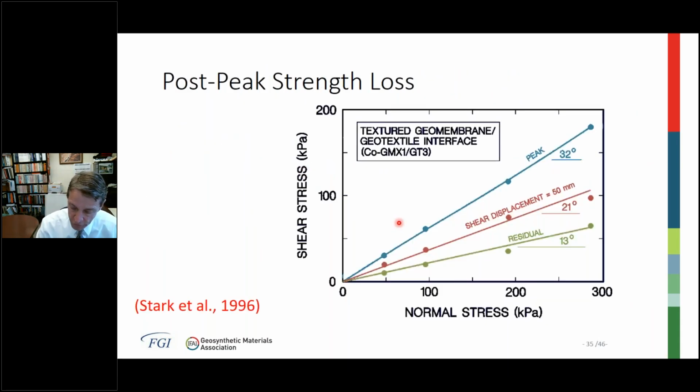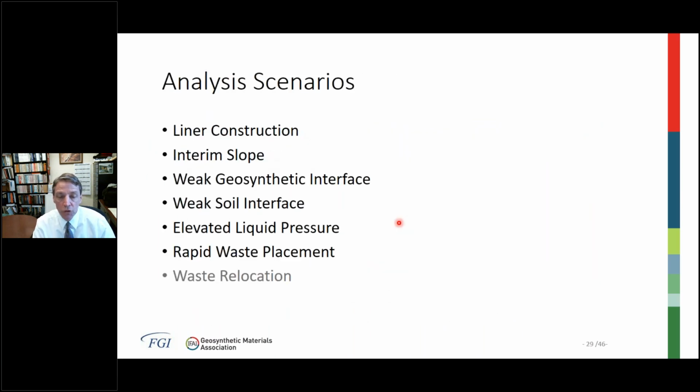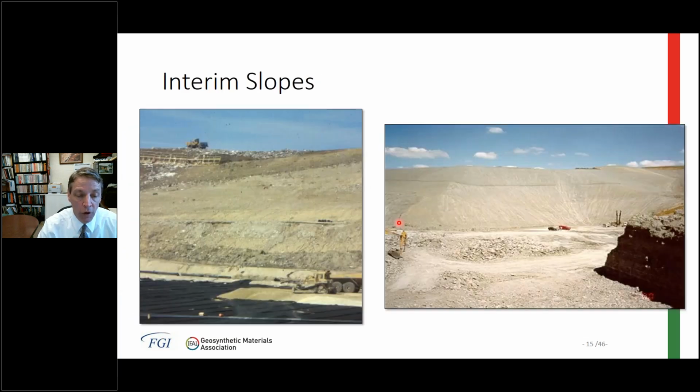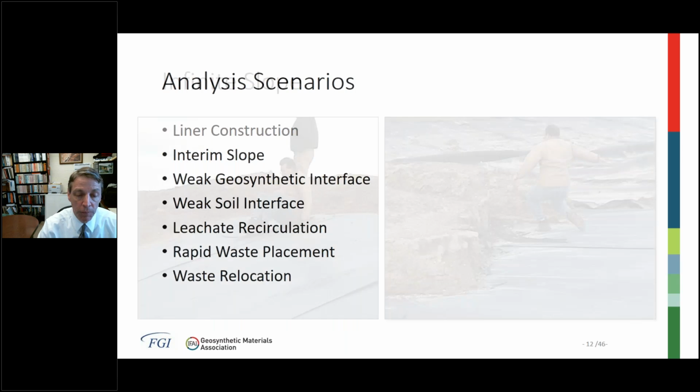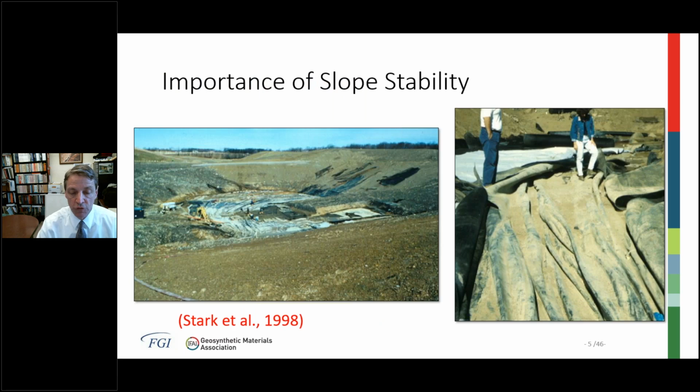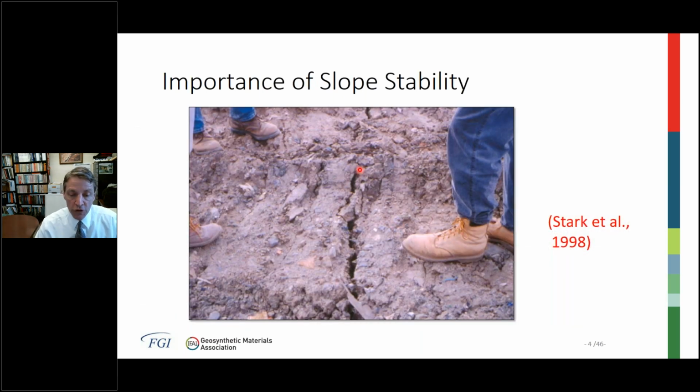That's really a great question, and that's the key to your field inspection, is deciding whether that crack is a tension crack or a settlement crack or an erosion feature. So I'm going back up to the case that I was using in the beginning to illustrate a tension crack. Here it is on the screen, and notice a tension crack is literally like a jigsaw piece. You could push those two sides back together and they would close up that crack exactly, so it just pulled apart.